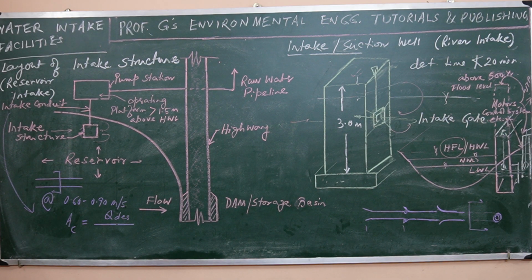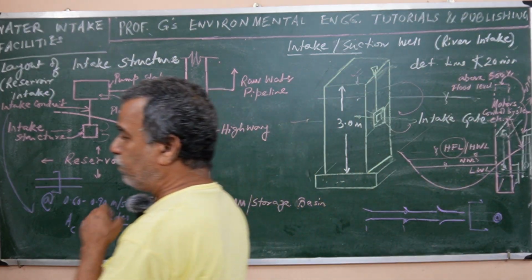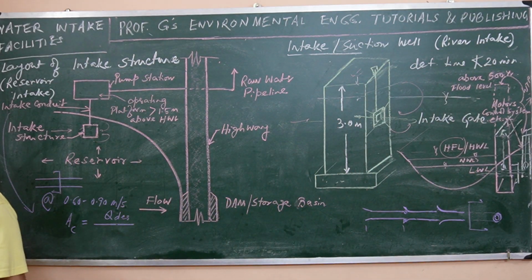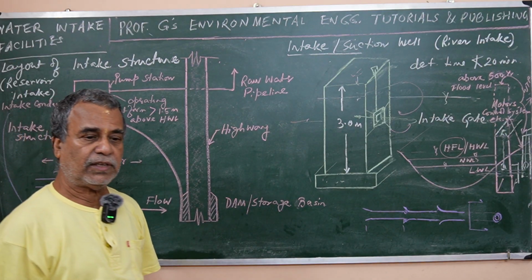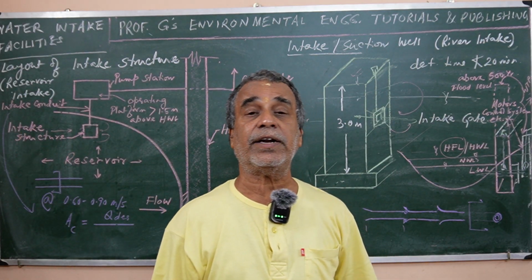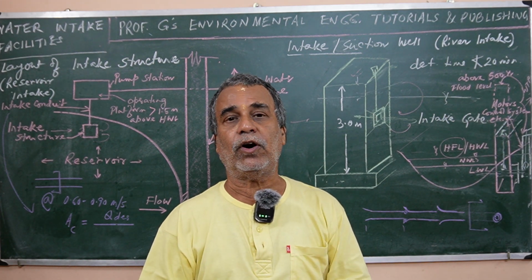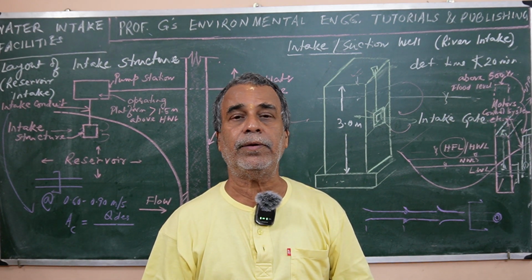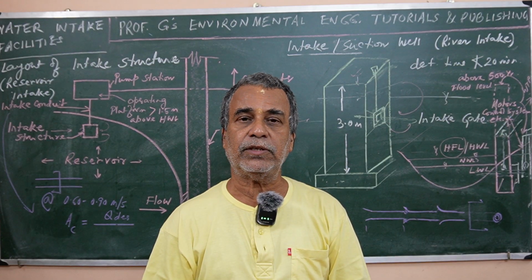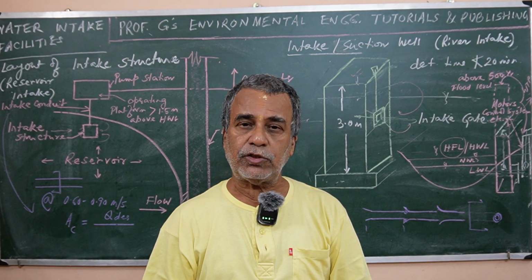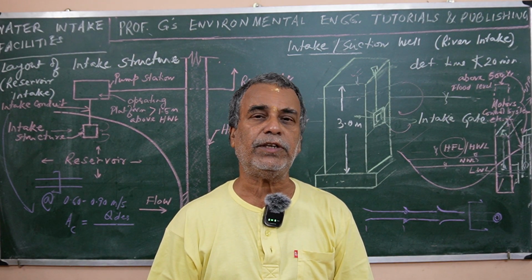So accordingly we have to design this one. And for pumps and motors, right? For the pumping system and these motors, these are required to be designed for 15 years or so, because the lifespan of these pumping machineries and pumping system is normally considered to be 15 years or so.